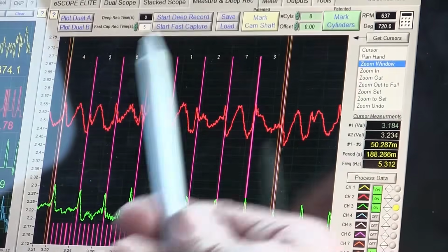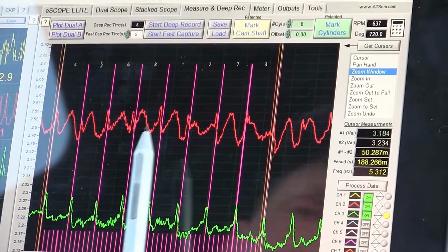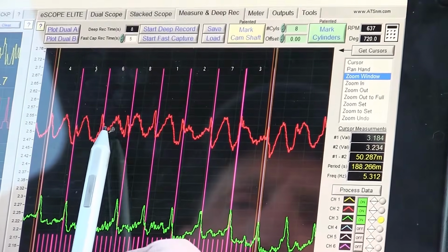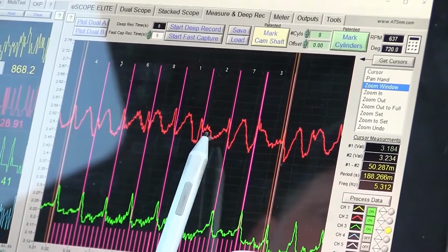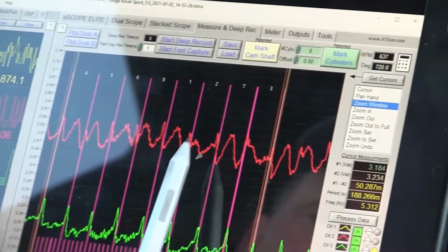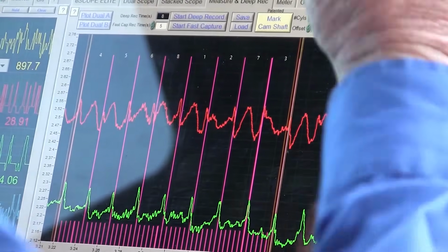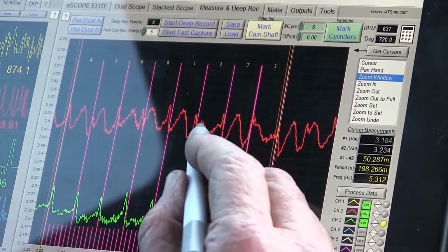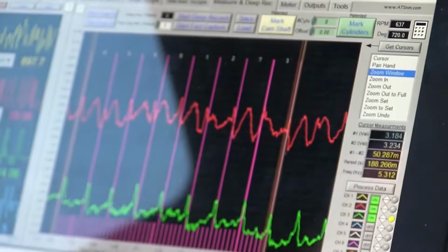Now that we're having the problem, do you see how 2 has a problem and 3 has a problem? And we go back here, and this... Okay, so what this is telling me right here is I think that's pump 1 that's having my problem. And we can see this guy right here. But this is a high pressure pump failing.